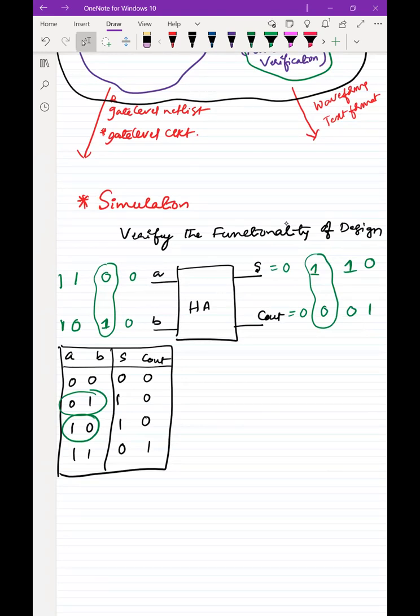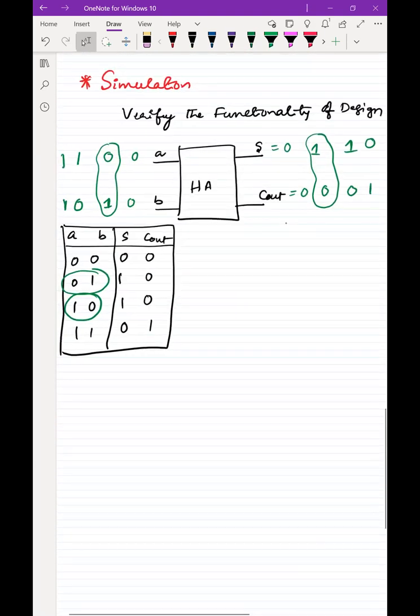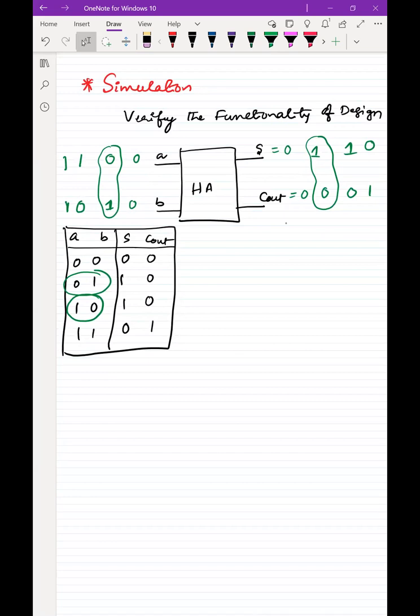Is it clear to all of you? Okay, so what is the fundamental behind this one? Whenever we want to verify the half adder, whatever the design may be, we have to apply the input signals to that particular half adder. Inputs we have to apply: 0 0, 0 1, 1 0, 1 1 we have to apply to this HDL program,